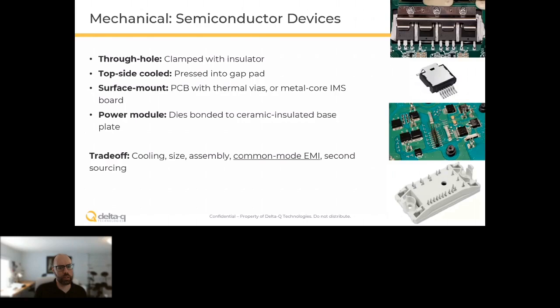But the one I want to particularly highlight is actually common mode EMI. There is unfortunately a direct trade-off where the better that you cool a device like this, often the worse the common mode EMI is, because the way that you cool a flat device to a flat surface is by having as thin of an insulator as possible and as much surface area. So essentially, you're forming a plate capacitor between two surfaces, and the more capacitance that you have, the more the switching noise can be injected into that heatsink. So there are direct trade-offs here for sure.